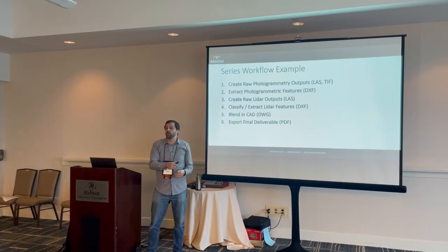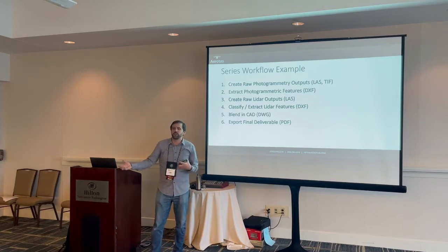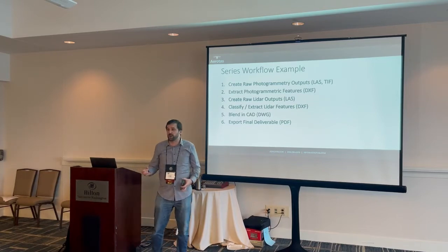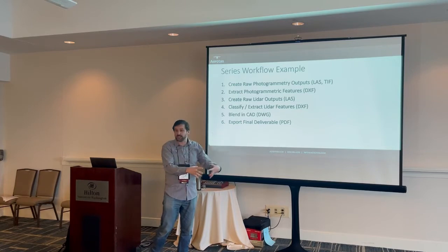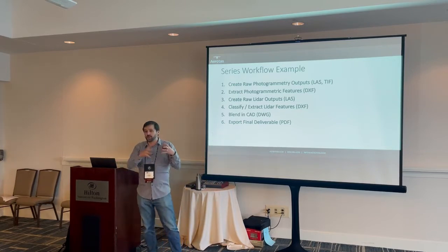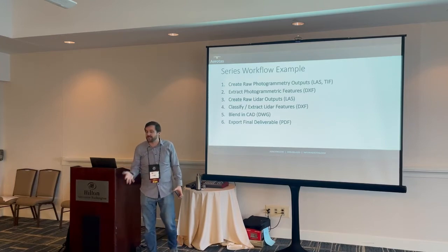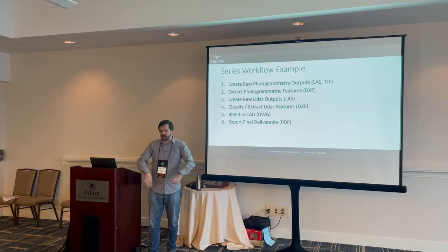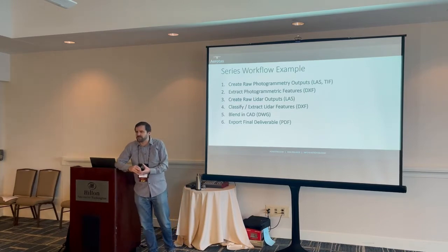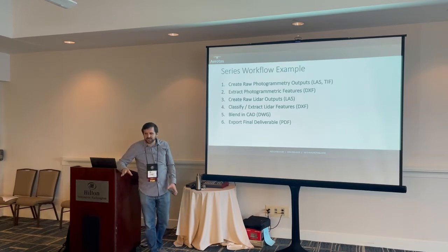And then once you get those into a DXF format, you can usually port it across different software, whether you're using a Lidar-specific software or a GIS software or even a CAD environment. We really like DXF as an intermediate output. That's a very common intermediate output for us, just because it's very compatible across different software and different formats. Does that kind of answer your question? Yeah, I'm just trying to say, yeah.